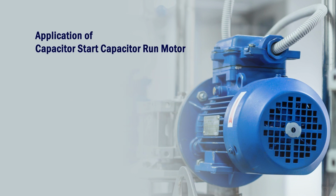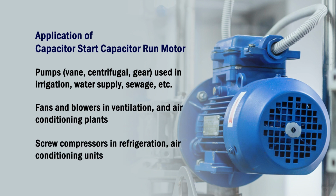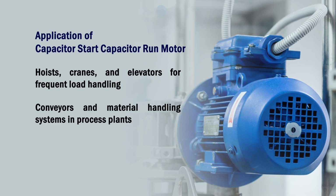The applications of capacitor start, capacitor run motor are they are used with pumps like different type of pumps, vane, centrifugal or gear arrangement, which is used in irrigation, water supplies, sewage, etc. These motors are used with fans and blowers in ventilation and air conditioning plants. They are used with screw compressors in refrigeration or air conditioning units. These motors are used in hoists, cranes, and elevators for frequent load handling. This type of motors are used in conveyors and material handling systems in process plants.